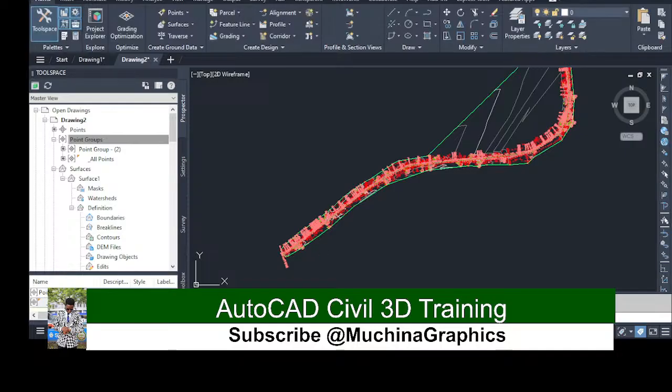So I click OK, and then the next thing you do is to come here, you click tangent with curves, so that you may not have problems because you have specified your design speed. So those tangents will be made depending on that design speed. So it will have done the most work for you.